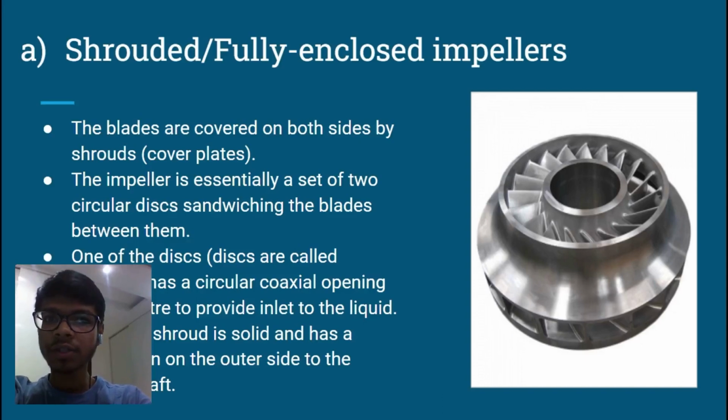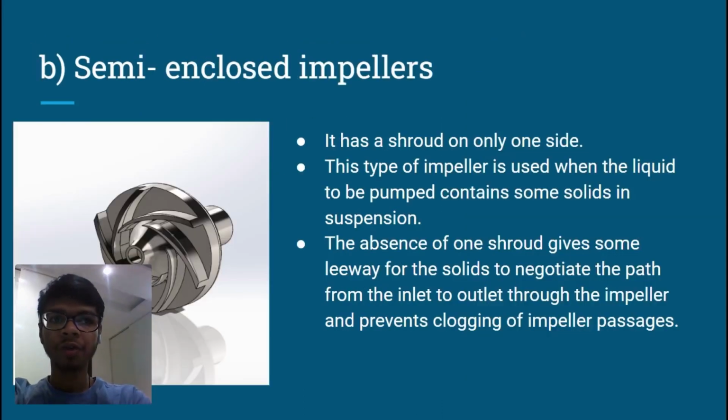So also there is no slippage of the liquid, and that is acted upon by the impeller. Also, the shrouded impellers are only used for clear liquids. So the clear liquids are those liquids which do not have suspended solids. So moving forward to the